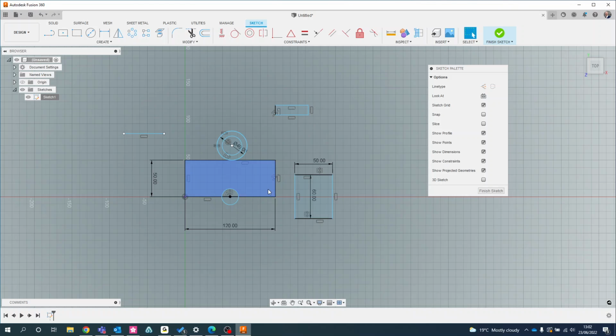You could go into the sketch and you could just drag one of these by accident and that moves your sketch. When everything is fully constrained, you can't actually move it. You'd have to go out of your way to modify the position or the dimension of a fully constrained sketch.